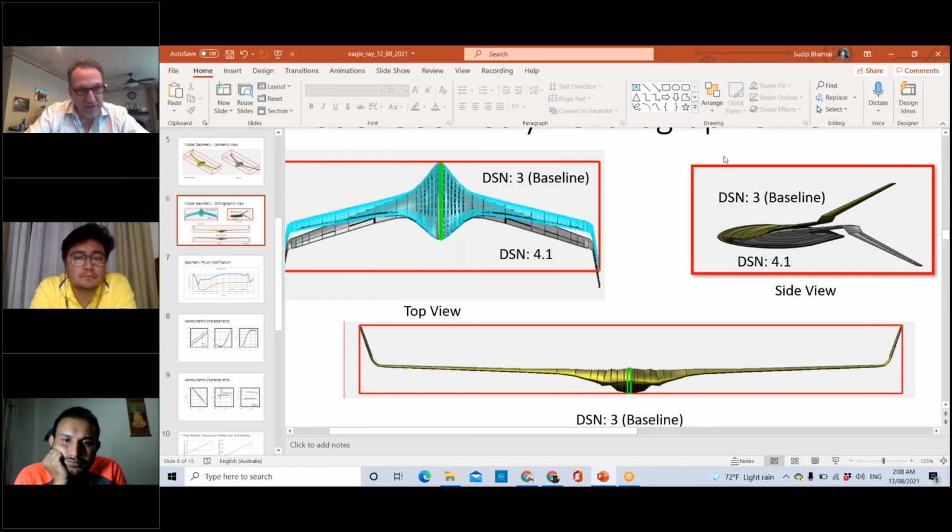We normally want it to stall intentionally right at the kink of the airfoil. So right where the body meets the outer wing, we tend to want it to stall there. And if it stalls there, it generally will pitch down and it will keep the ailerons and elevons happy, and nothing on the outer tips will stall. Once one of the tips stalls, it'll spin and it'll happily stay on that spin forever. So we will want to take a look at that. And that might be, let's look at the slide 7.